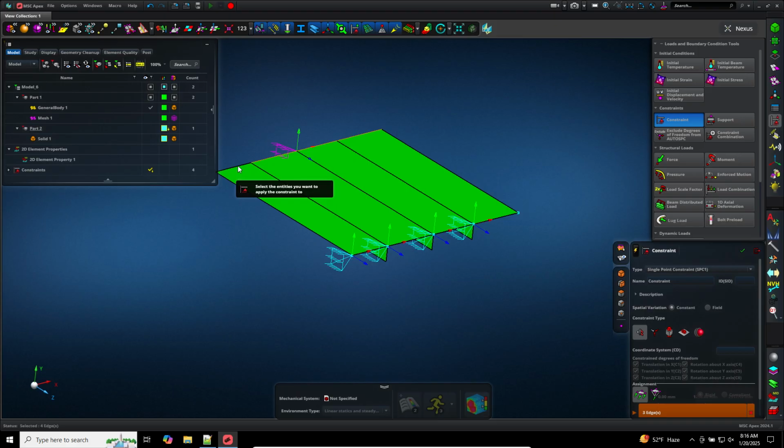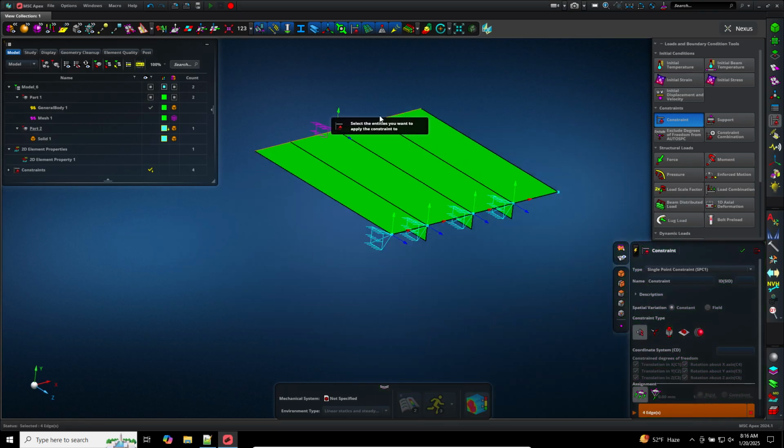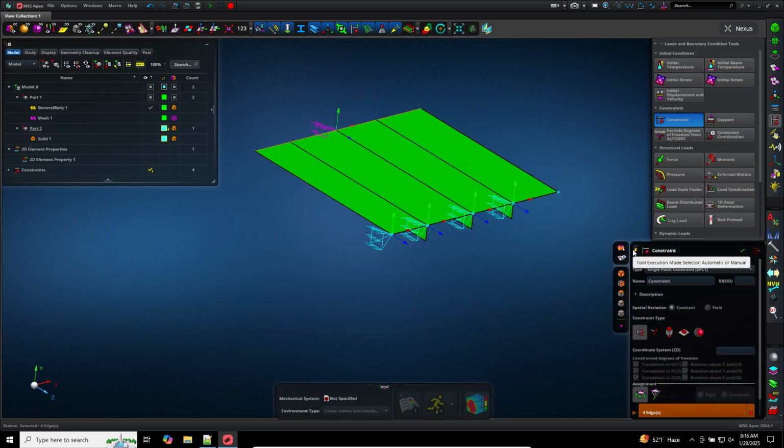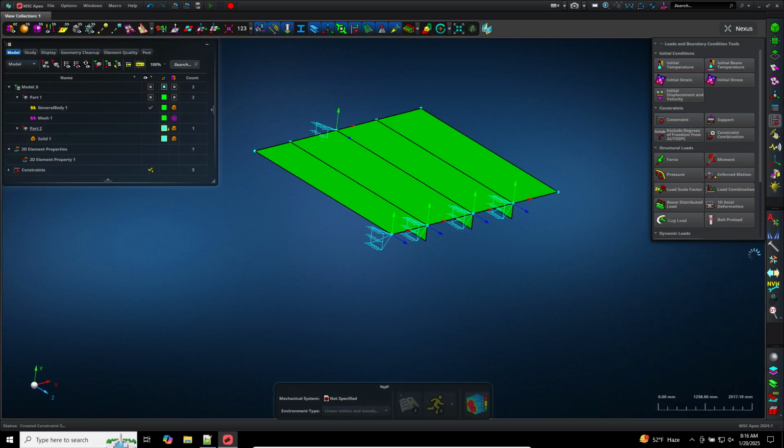I've selected 4 edges, and if you zoom in, you notice that the edges are orange, indicating that I've selected those edges. Now the lightning bolt is off, so it doesn't automatically execute the action. Click the middle mouse button, the scroll wheel, or MMB, and now it performs the action, and now it's created my constraint. Exit this.